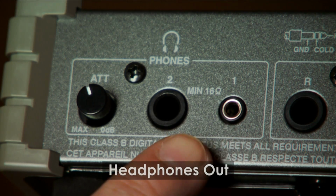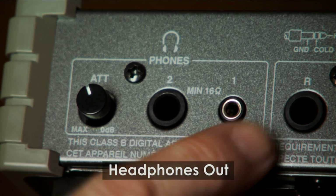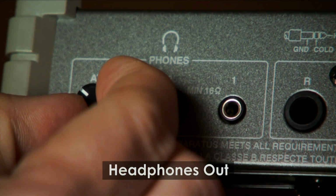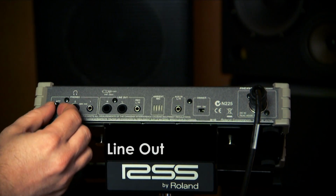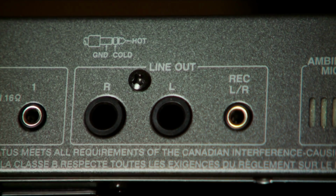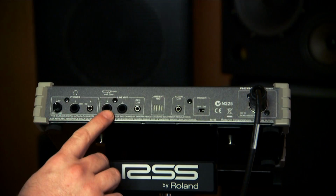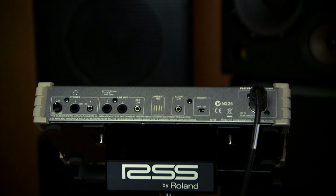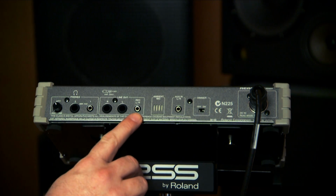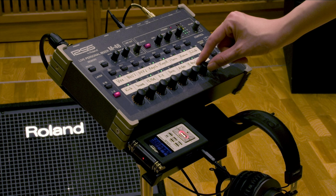On the back, you find connectors for 1/4 inch or 1/8 inch headphones or in-ear monitors. An attenuator sets the correct range for your headphones. Balanced line outputs are available to drive powered monitors. This output can be switched to a sub-output with internal low-pass filter, particularly useful for a drummer on headphones who just needs that extra thump from a subwoofer or the rumble of a low-frequency shaker. The stereo recording output is great for connecting to a recording device like Edirol R09HR.